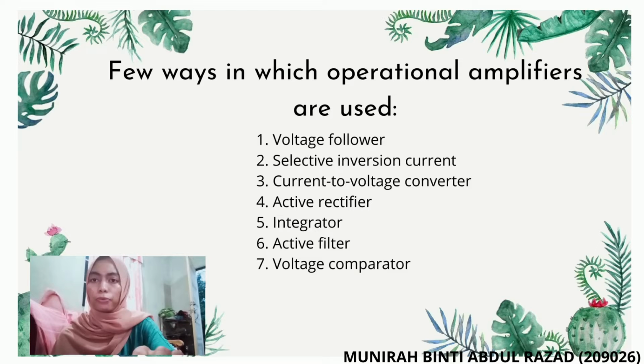There are a few ways in which operational amplifiers are used. They are used as a voltage follower, a selective inversion circuit, a current to voltage converter, an active rectifier, an integrator, a whole wide variety of filters, and the last one is the voltage comparator.